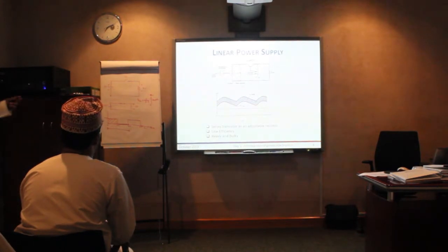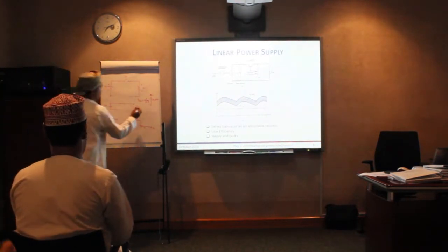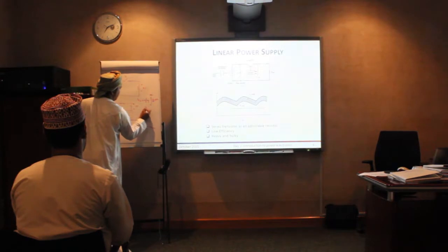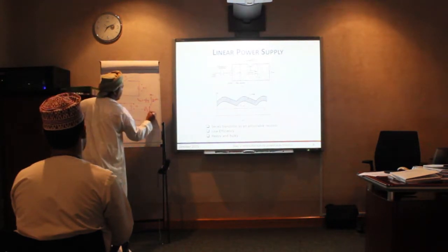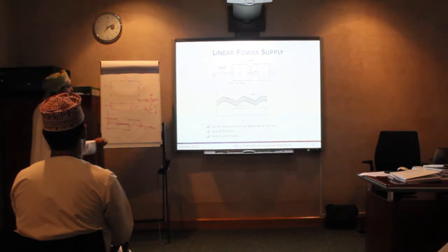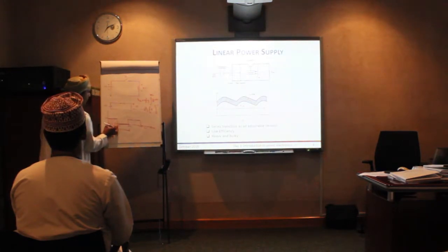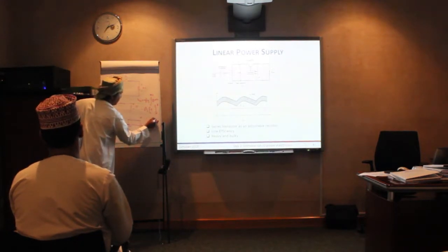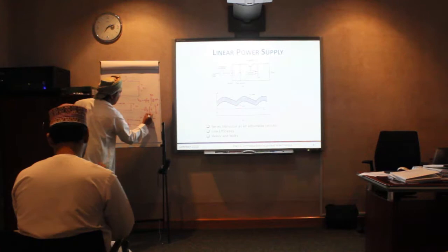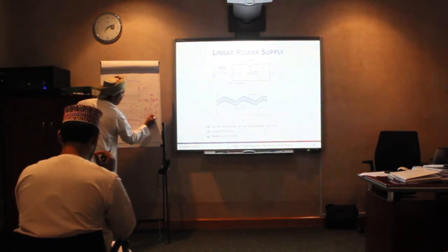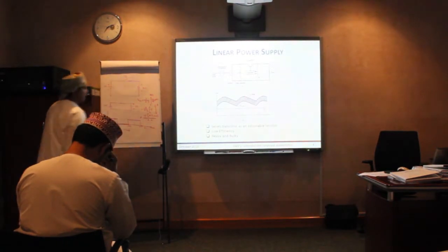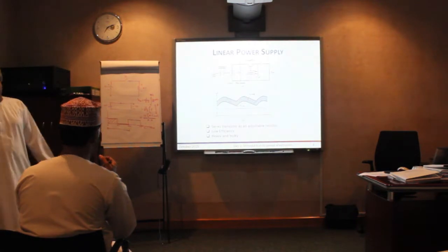So now if you just integrate it, this is constant, 10 over 0.2, right? And then t from 0 to 0.1, because this is the on time, right? So 0.1. And then you will get 10 multiplied by t, which is 0.1 minus 0, over 0.2. If you look at this one, you will get 5 volts, right?